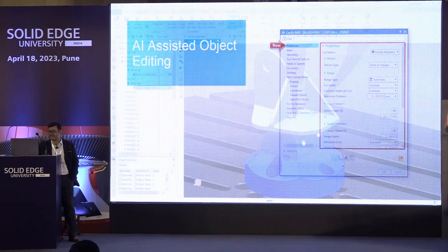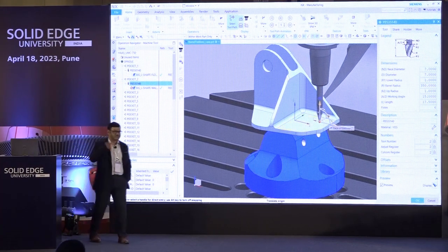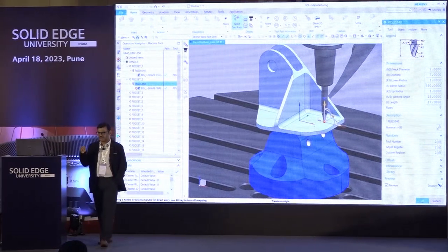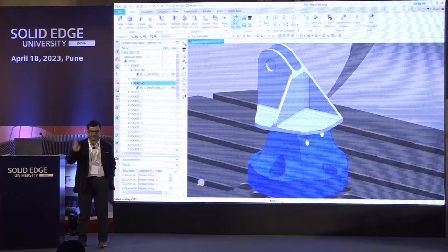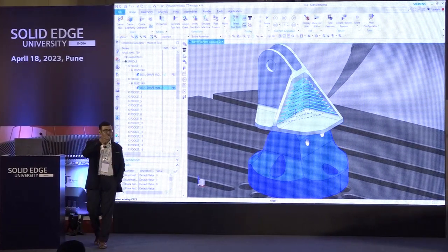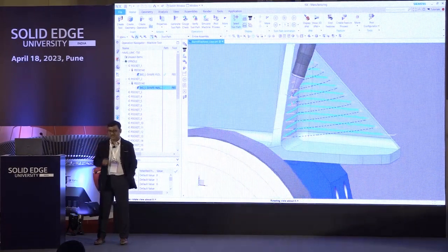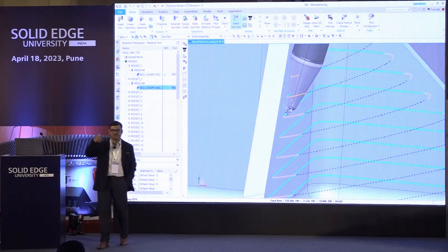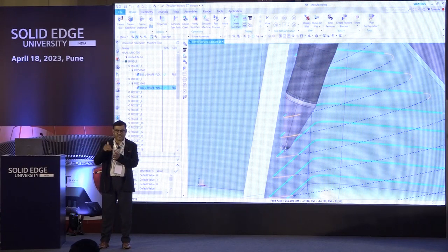These are all just glimpses. I'm not telling all. Normally, we recommend don't just go for toolpath validation. We recommend you go with digital validation. That's a recommendation for the safety of your machine, because when you load Solid Edge CAM Pro along with the part, it is always easy, but you can't visualize whether the machine will go and touch the part, right? Is there any collision between the part and the assembly?